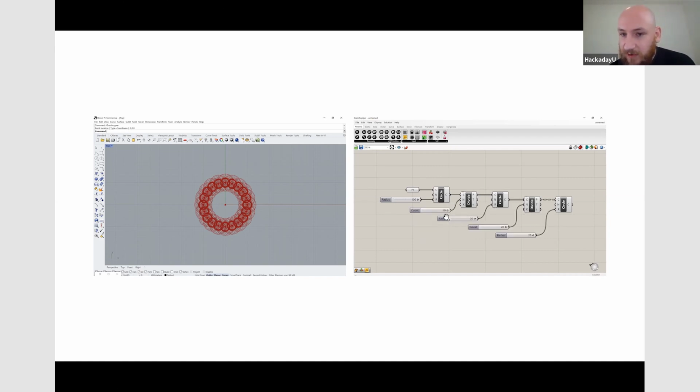Rather than have multiple sliders, if I wanted the same number to be controlled, back to like in the Rhino model, when I want fewer points on a NURBS curve to have control over it, I want fewer sliders. So for the division points, I can just use one slider and plug this slider into both division points and this slider into both circles. That's currently set to 20. And if I change the number of division points down to 10, that will reduce the amount of geometry in the model because all of these circles are based on the number of division points. Therefore, it's a bit cleaner here.